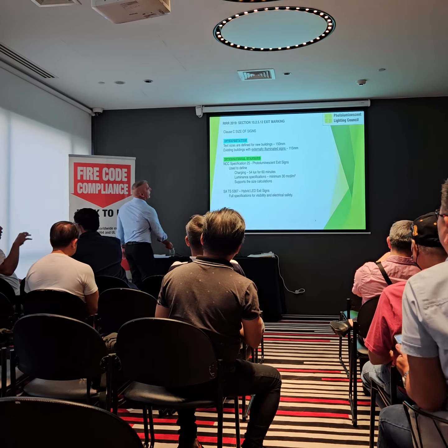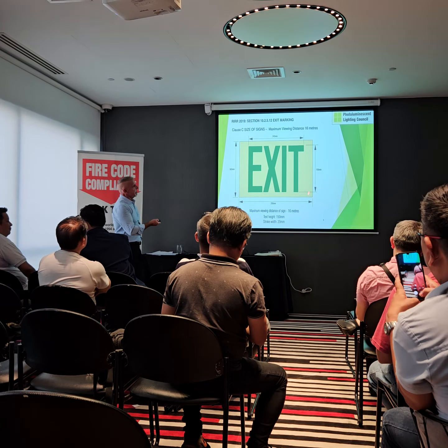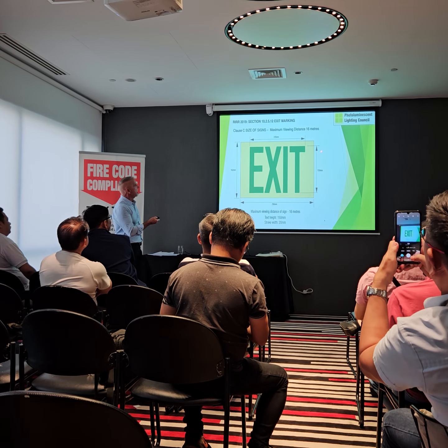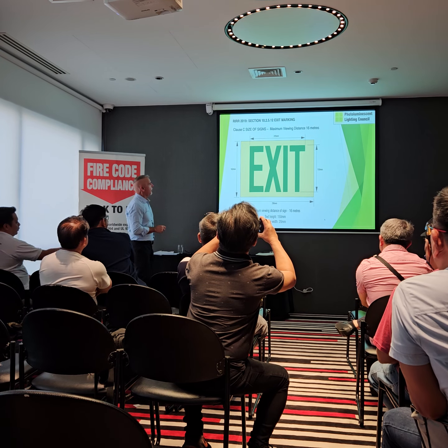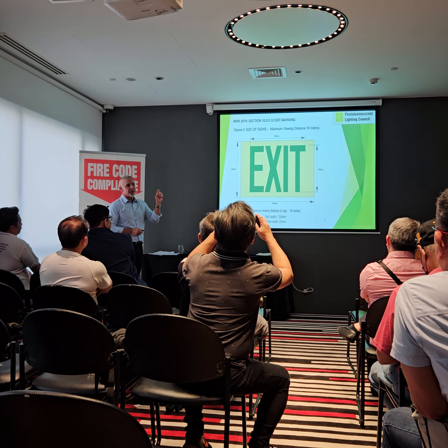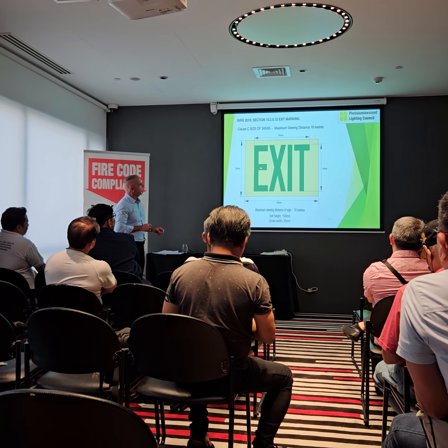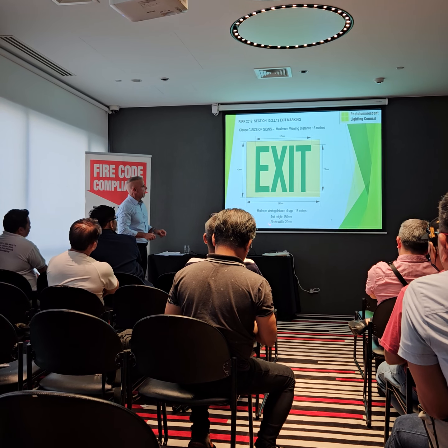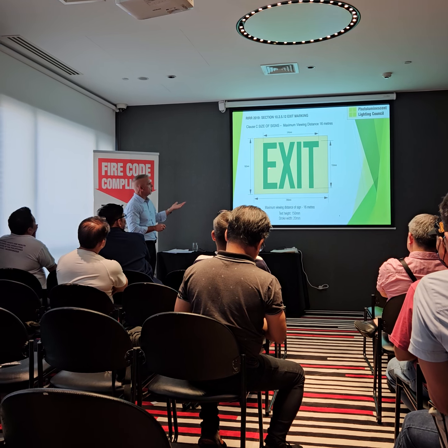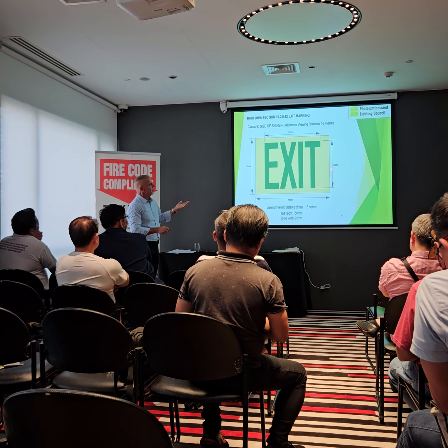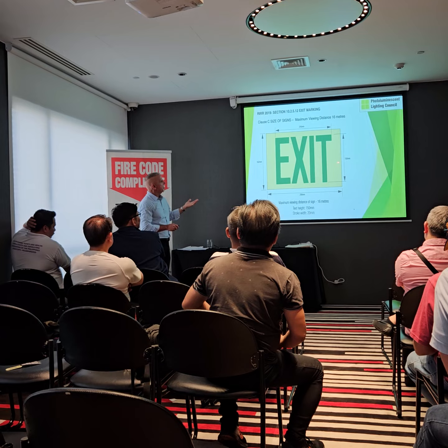Right. So, what does all that make? Rightio. So it talks about 150 millimetres high for the text, and it talks about what in the rest of the world is called a stroke width. It talks about 19 millimetres, and that's defined in the font as the width of the font. So we've said here the stroke width is 20 millimetres because it fits better to the usual sign dimensions. So 150 millimetres high, generally,